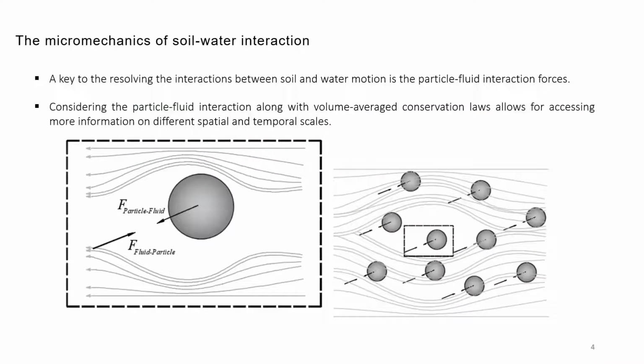And the key element to achieve this coupling is the particle-fluid interaction forces. So keep in mind, now we're not looking at soil as a continuum mass that is essentially larger than a representative volume element. Rather, we're diving into the micro scale where soils are individual particles that affect the surrounding fluid and vice versa.